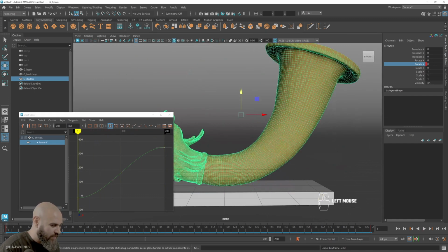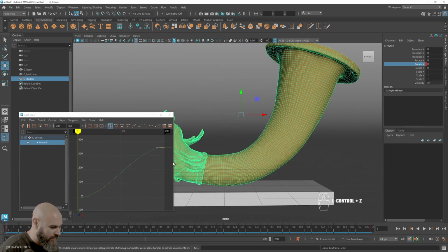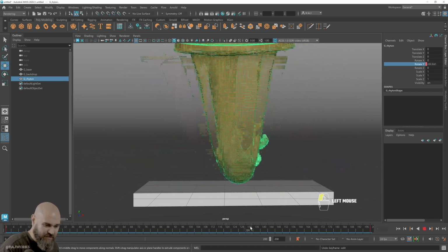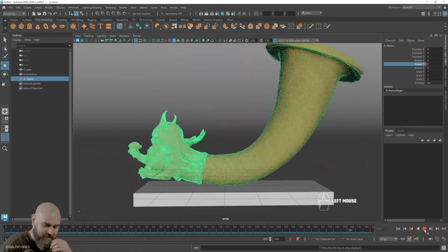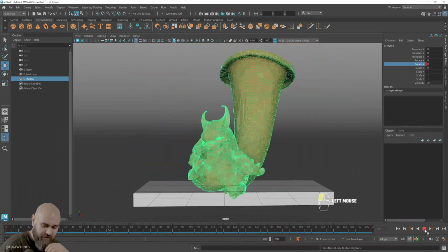So it's good to know about the graph editor when you get more into keying, overshooting, easing in, easing out, and manipulating these keyframes. You can always change how the turntable moves. But for now, for beginning, just get in the habit of setting some keys and viewing your animation, seeing how long you want the keys to go for.